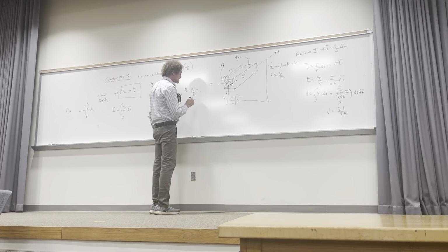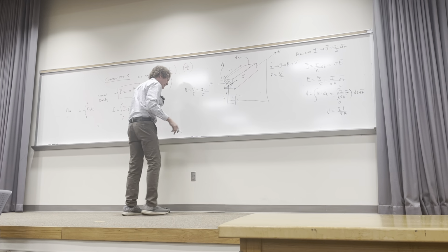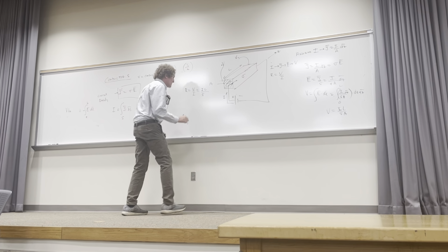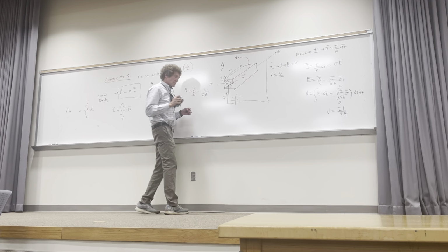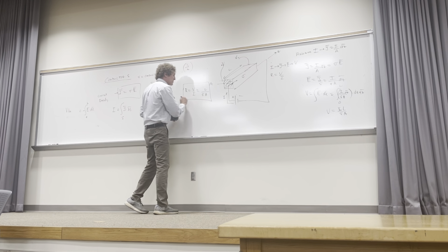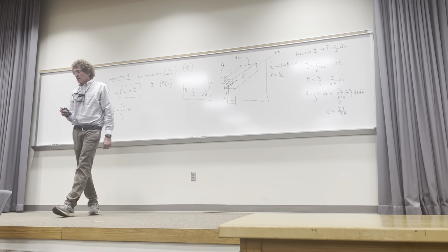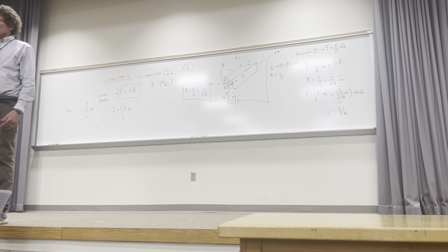There it is, V, so I have really I L over sigma A divided by I, and it would be this. Y'all follow me, class? And that would be the resistance of a bar between the ends of the bar if you had a constant cross section, the cross section is invariant with length, and sigma is a constant. Y'all follow me?